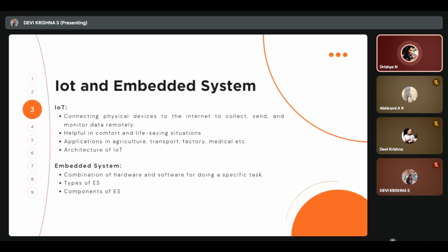Here is how IoT architecture is typically layered. The first layer is the sensing layer, where devices like sensors and actuators interface with the physical world. The next layer is the connectivity layer or the communication layer. This layer handles the connectivity between the device and the rest of the system through wired and wireless protocols and gateways. The next layer is the data processing layer, which is responsible for storage, processing, and analysis of data from devices. This may include edge computing, cloud, and analytics. The next layer is the presentation layer. It provides interfaces and use cases such as mobile apps, dashboards, and automation systems for end users.